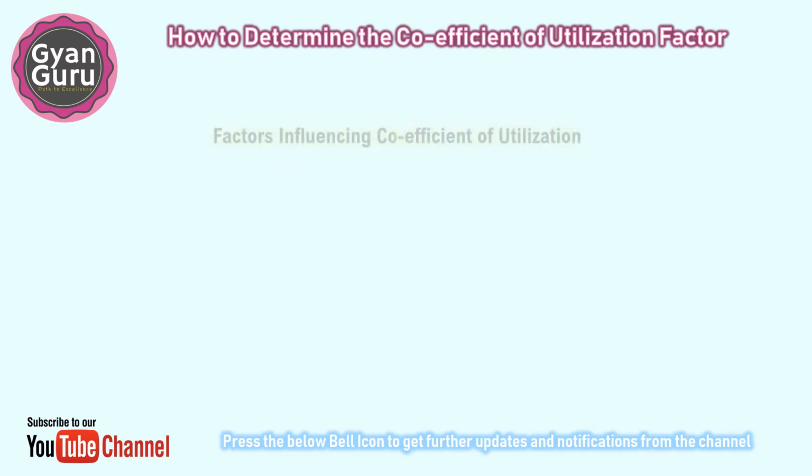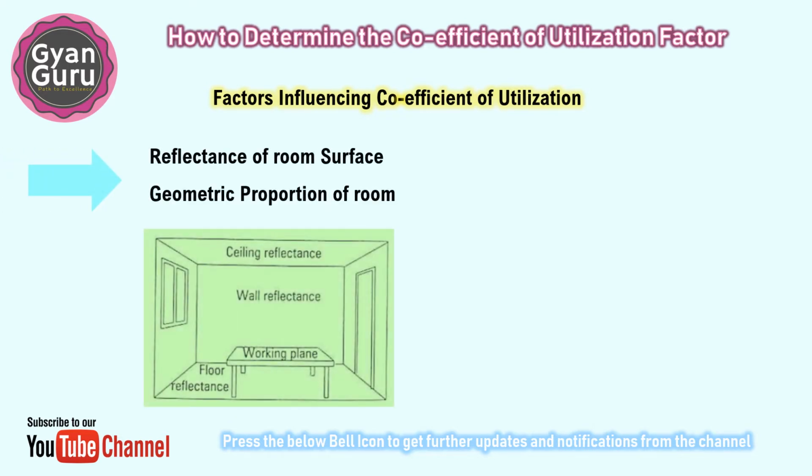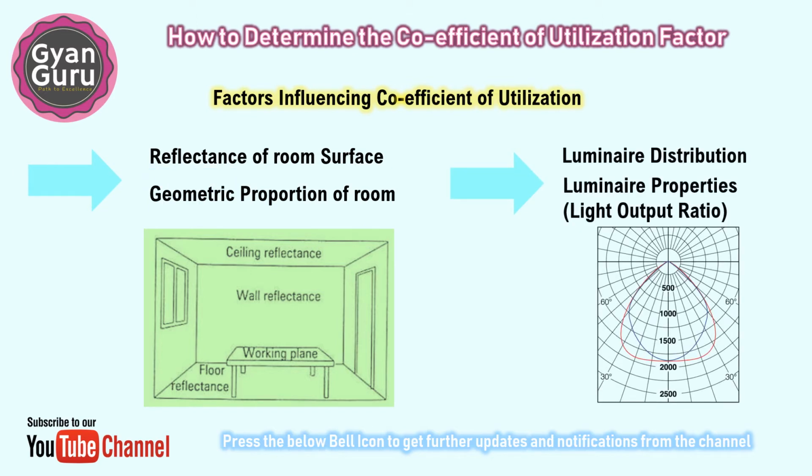The factors which influence the coefficient of utilization are reflectance of room surfaces, geometric proportion of the room, luminaire distribution, and luminaire properties such as light output ratio, efficiency, photometric properties, etc. One by one we will explain these factors and their significance in lighting design.